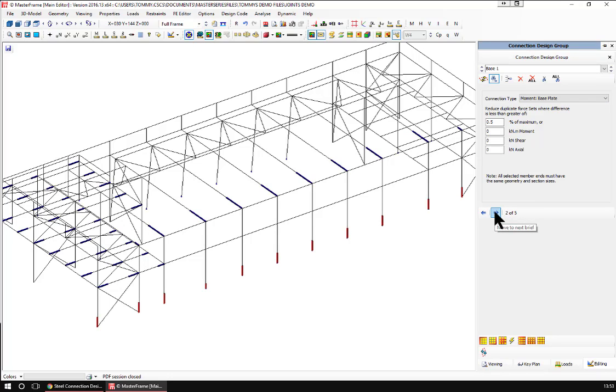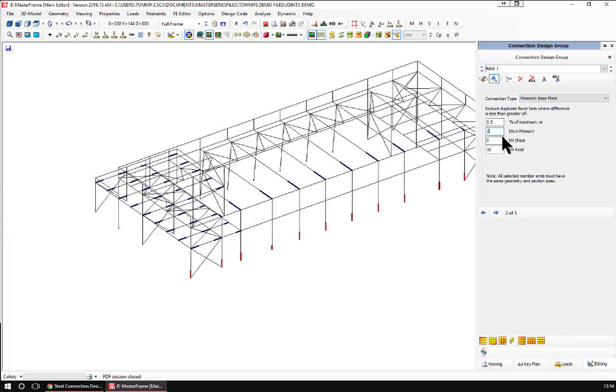These are all my axial bases, and I'm going to ignore anything within 10 kilonewtons of each other for the axial moments, and anything within 1 kilonewton for the moment. And that's to do with the number of loading cases. So if you had 6 joints with 6 cases each, they may end up with only 7 cases because most of them are matching the first set very closely.